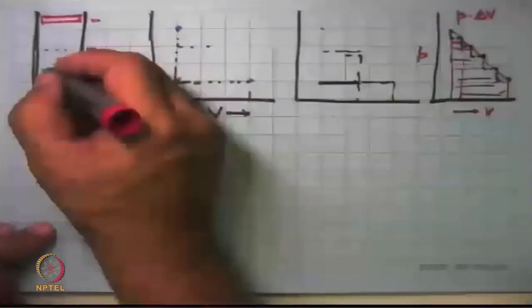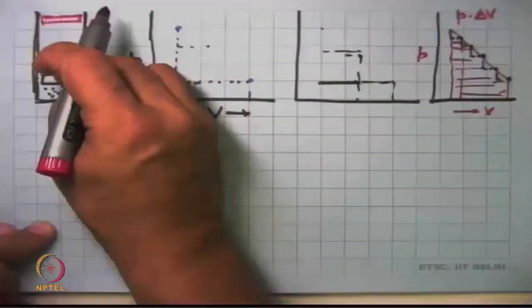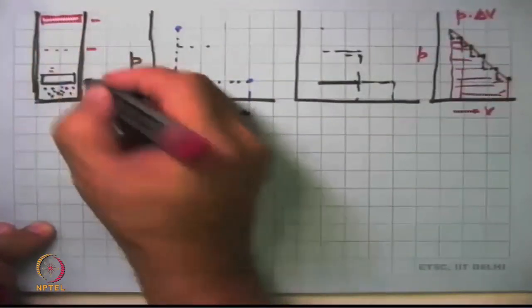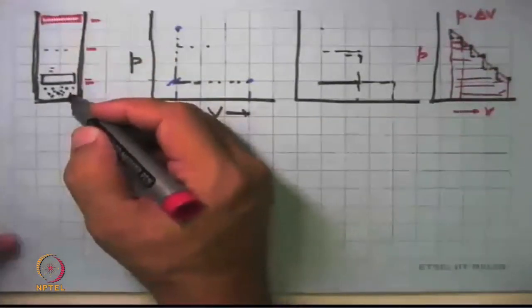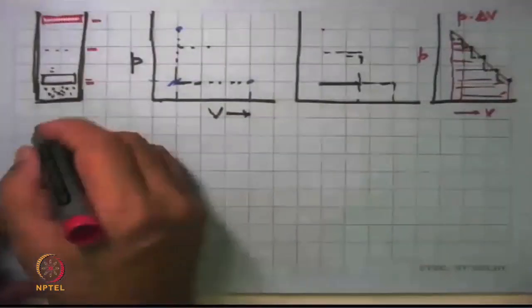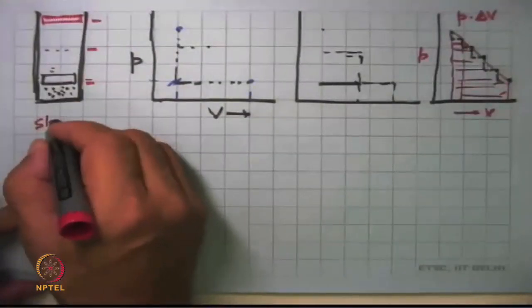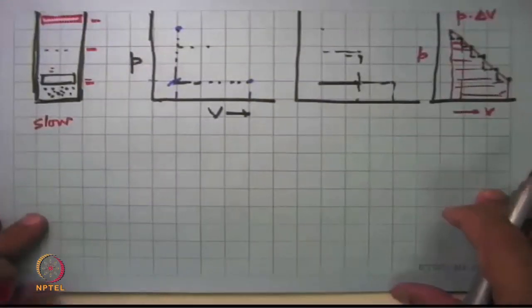It would also mean that the pressure should change in very, very small steps. The piston should move very slowly, and by a very small amount, so that the system immediately comes back into equilibrium or never really deviates from equilibrium too much. Such a thing would be very, very slow, and nobody is going to wait that long for an engine to produce power.